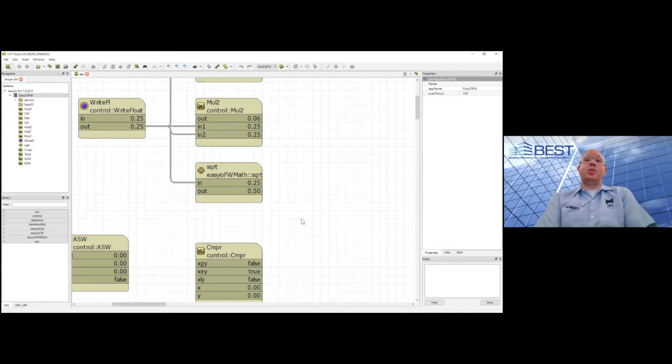I don't start students off with complex tasks like we are doing. I start my students off when they first see this program on the rooftop unit exercise. So they are taking over control from a local thermostat for a two-stage heat, two-stage cool rooftop unit, so that all of the work that they're doing with analog is all temperatures that they're familiar with: room temperature, set point, things like that, differential.